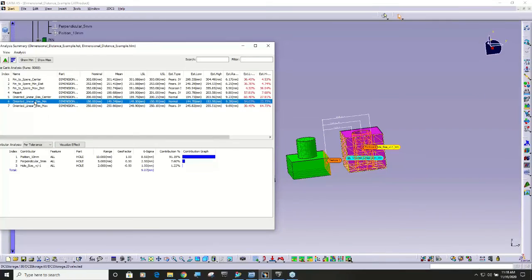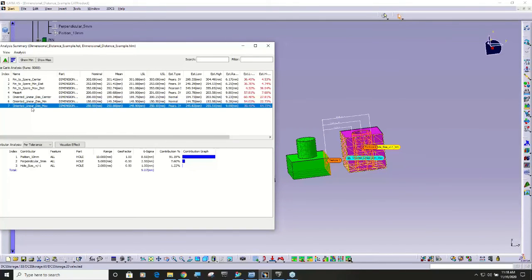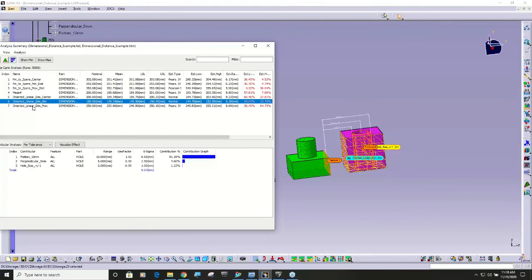For the distance measure, in CATIA v5, will the mesh setting affect the measurement if measuring to or from a cylindrical feature? No. Again, because we are essentially taking this feature and representing it with internally a point at the bottom, the middle, and the top.